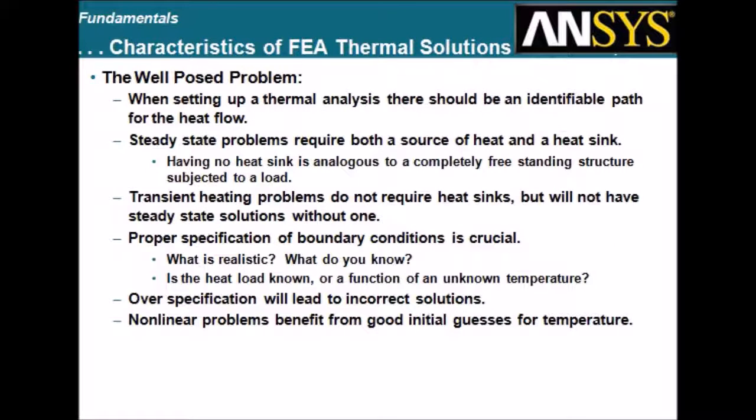The well-posed problem: when setting up a thermal analysis, there should be an identifiable path for the heat flow. Steady-state problems require both a source of heat and a heat sink. Having no heat sink is analogous to a completely freestanding structure subjected to a load. Transient heating problems do not require heat sinks, but will not have steady-state solutions without one.